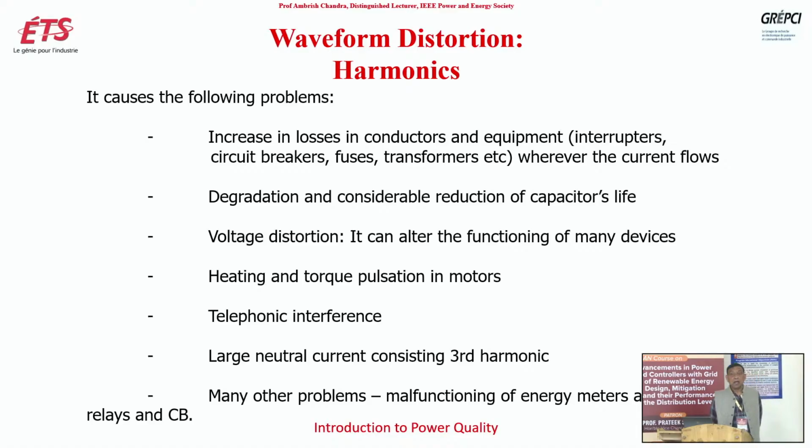And so the fifth harmonic will generate torque in the opposite direction, and it will have a frequency 5 times the fundamental. Although the amplitude is 1/5, still it has some parasitic effect.